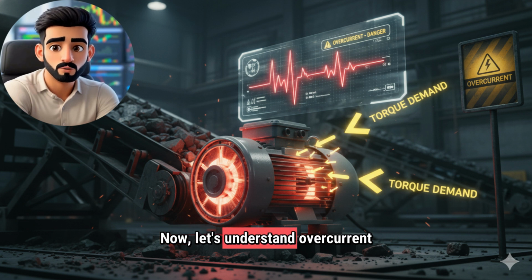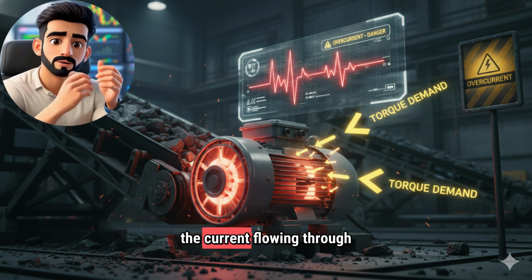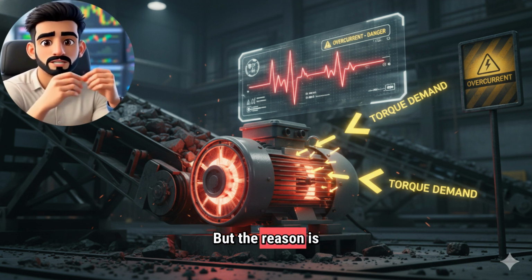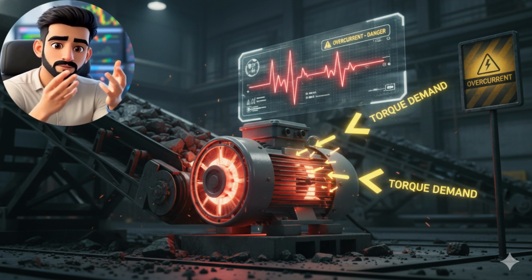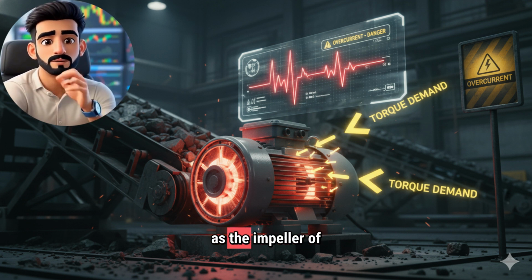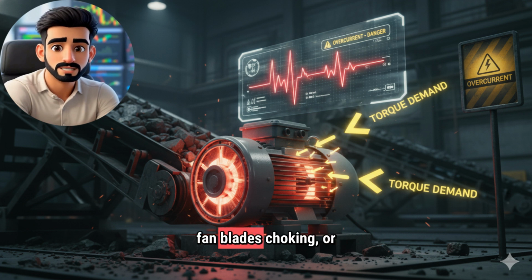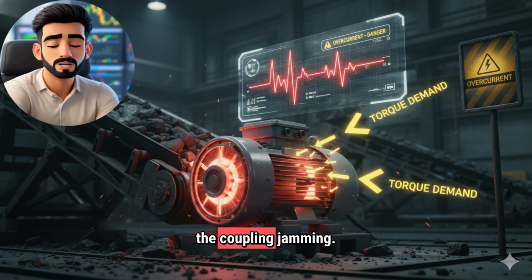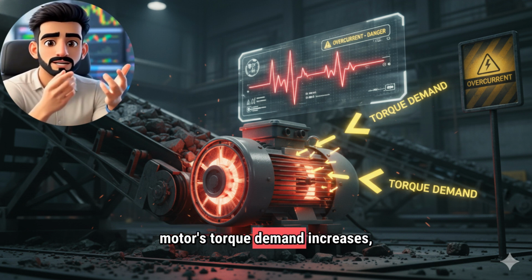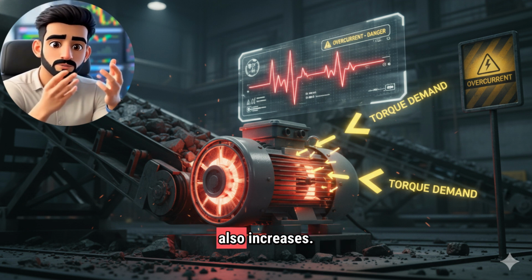Now let's understand overcurrent protection in detail. Overcurrent simply means that the current flowing through the motor exceeds its rated current. But the reason is not always the same. Often there is a sudden increase in load on the motor, such as the impeller of a pump jamming, material jamming on a conveyor, fan blades choking, or the coupling jamming. In this situation, the motor's torque demand increases, and according to the torque formula, the current also increases.